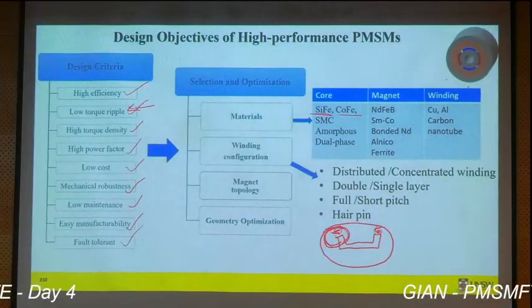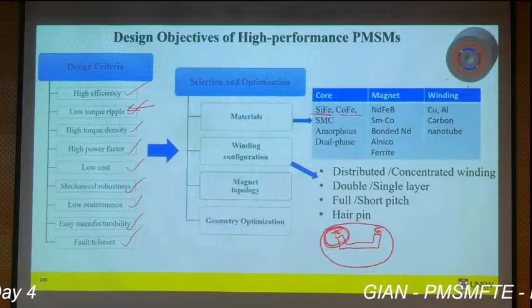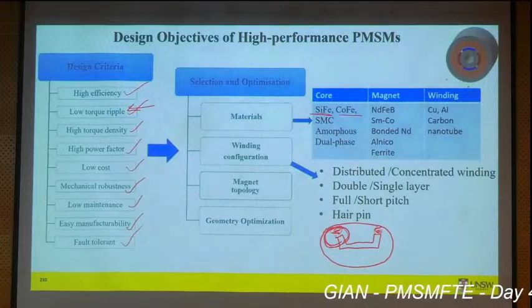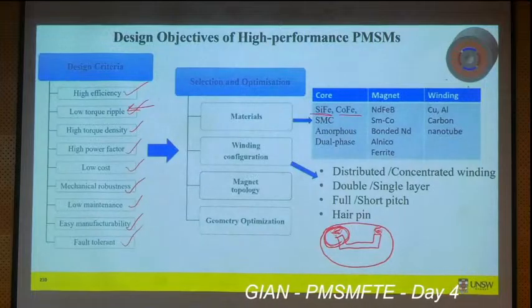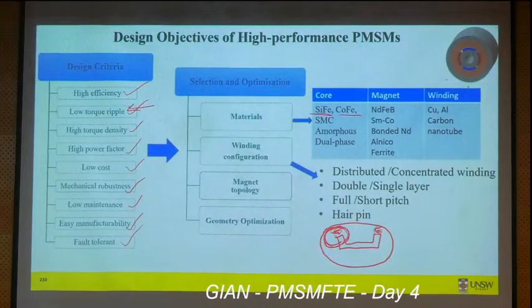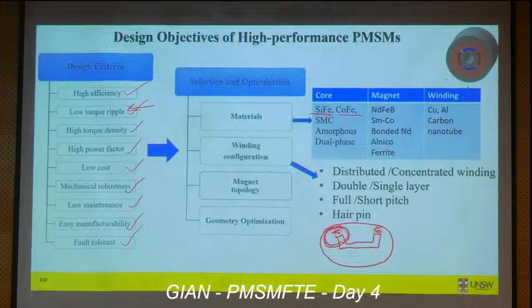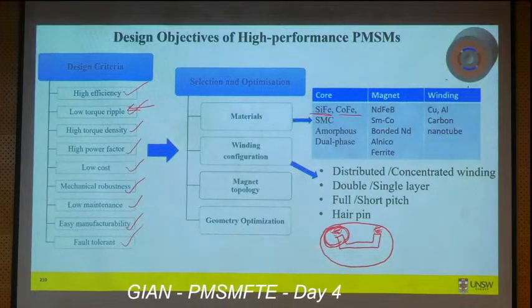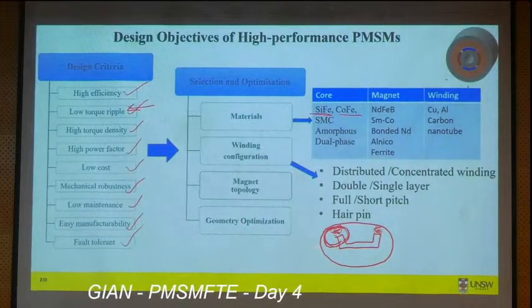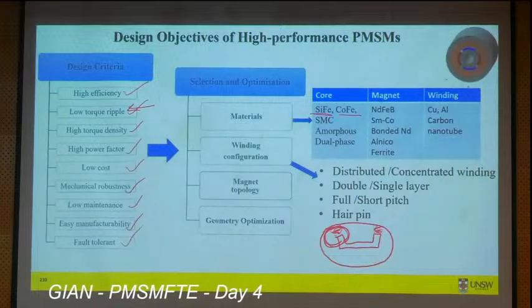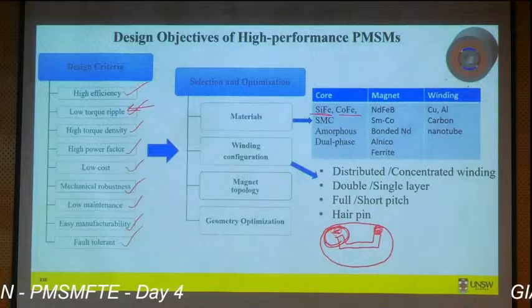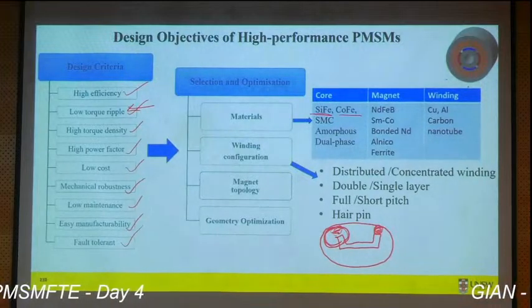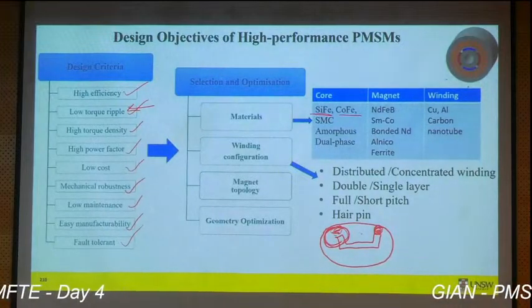Now, so we are wasting some of the magnetic flux here. Okay, but it's necessary for IPMSM, and it is also necessary for the synchronous reluctance machine to have the thin bridges to improve saliency. But if we could use dual phase material, this part of the material we can make non-magnetic, okay, and the rest is magnetic.